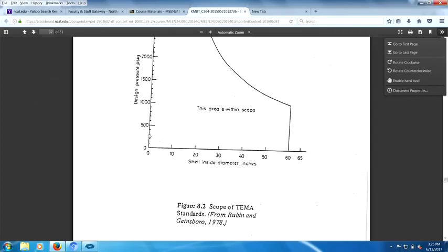There are two other major heat exchangers we're going to talk about. One is a plate heat exchanger, and the other one is a spiral heat exchanger. Their upper limit is 300 PSI, right? So right across here, you can see those two other heat exchangers can work absolutely wonderful. But you can see what the shell and tube can do for you. Just to give you an idea. All right, and I already said you can go up to 10,000 PSI easily.